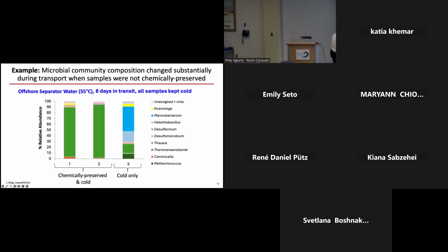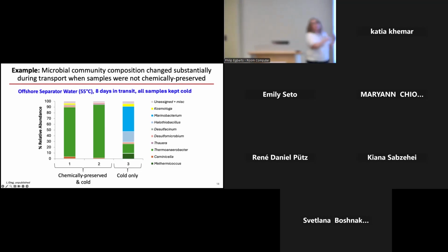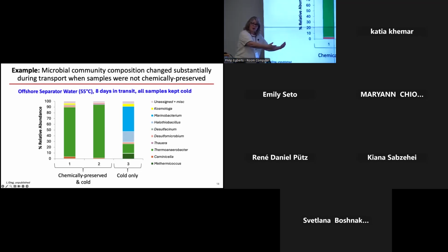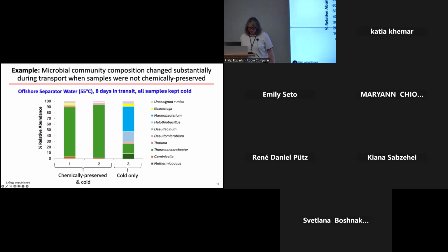So it's really, really important to have a preservative in your sample vessel, collect properly with clean tools, and then you can really trust the data afterwards, or the data at least makes sense with the environment from which it was collected.